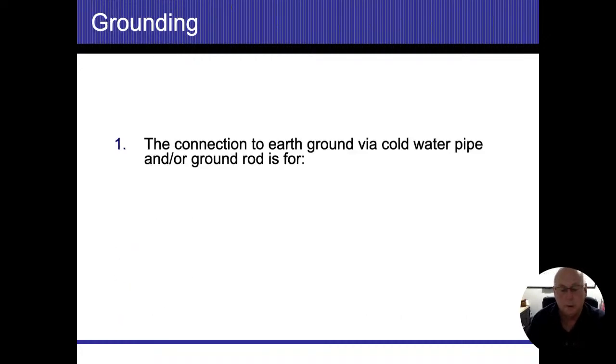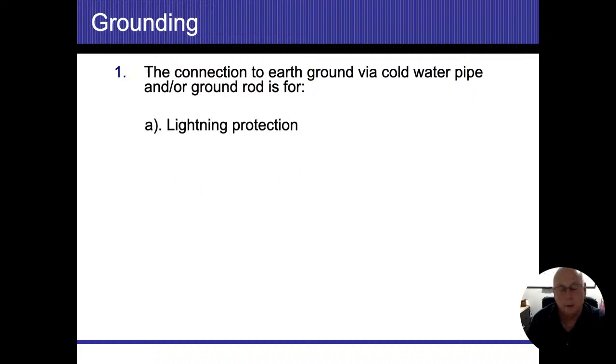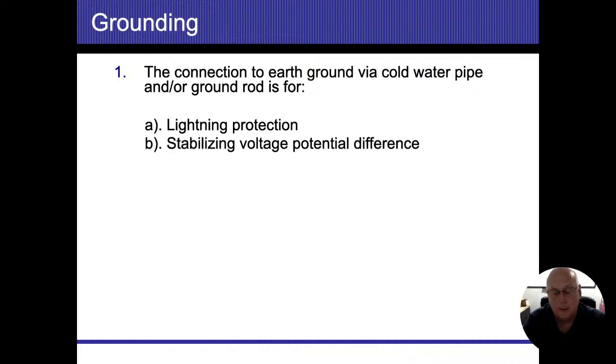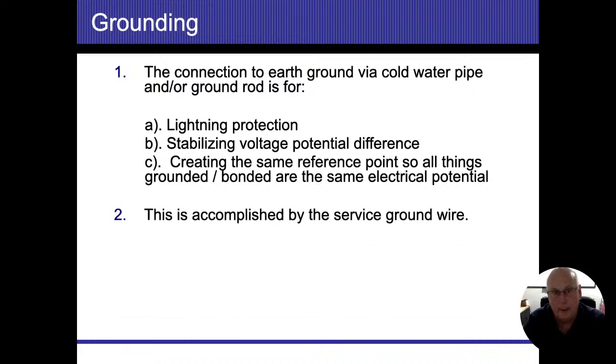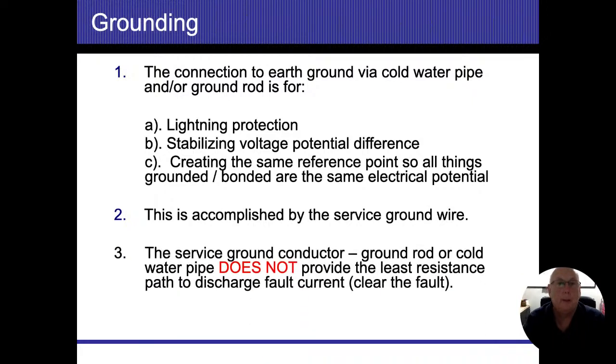Different types of grounds. Let's go back to this one here. And different types of grounds that we're going to run into. So here it mentions the water pipes. We already talked about the ground rod outside. Some areas of our country, they don't have soils where they could dig into. Sometimes they're on bedrock and they can't take that piece of steel in there. Sometimes it's going to be on a slab. Different things that we can use for a good connection to the earth, item to earth.